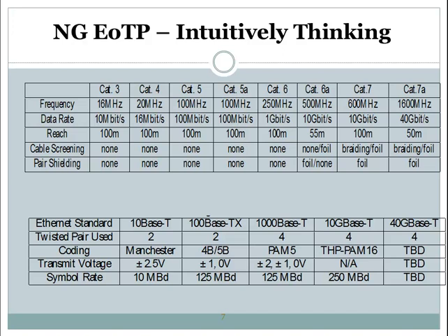And for the Ethernet standards themselves, we use higher order modulation schemes, from the basic Manchester code up to PAM16 with a THP precoding system. And thanks to the expanding frequency, the symbol rate has also increased from 10 megabaud to 250 megabaud per second now.